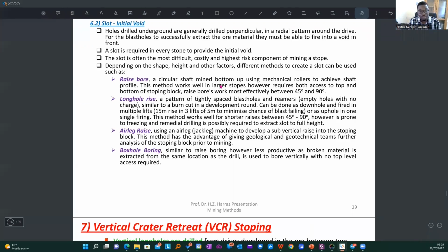That is how come when we have storey buildings, we have certain heights we go up to and we floor the top of the building. Because if you go too high, there will be stresses within the wall and your building will not last. In the same way, when you are underground and you are creating the space where you are working, you need to be cautious. So before you go for this type of long hole or long wall drilling, you have to be very sure that you have a very competent country rock, and at the same time, the ore you are dealing with is strong enough to last through the period when you are doing your activities.